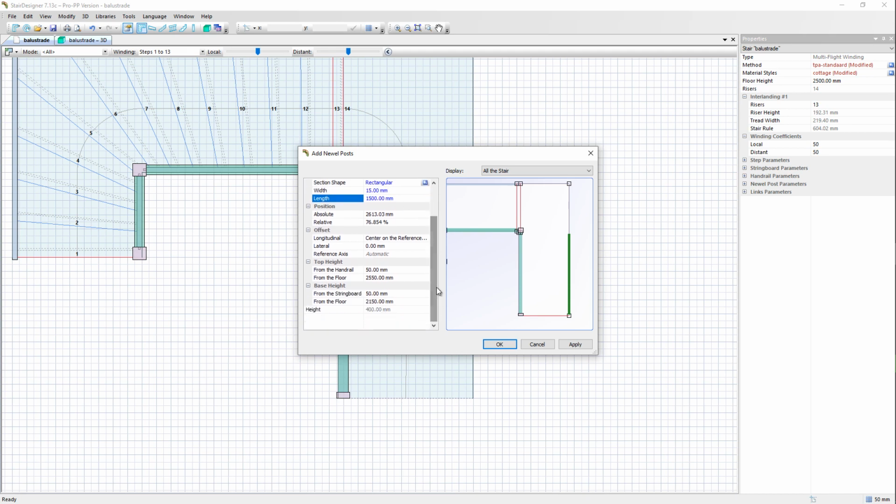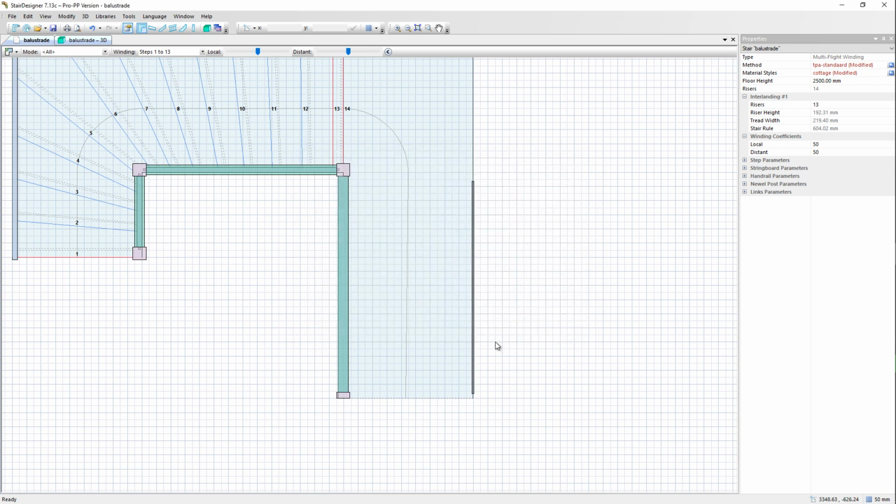Now we are going to check its position. So the top height will be on the floor, 2500. The lower part will be equal to the lower side of the floor. It's 300 millimeters, so it will be around 2200. Okay, so we already sized up that item. We will say apply. Okay, so it's sitting here.